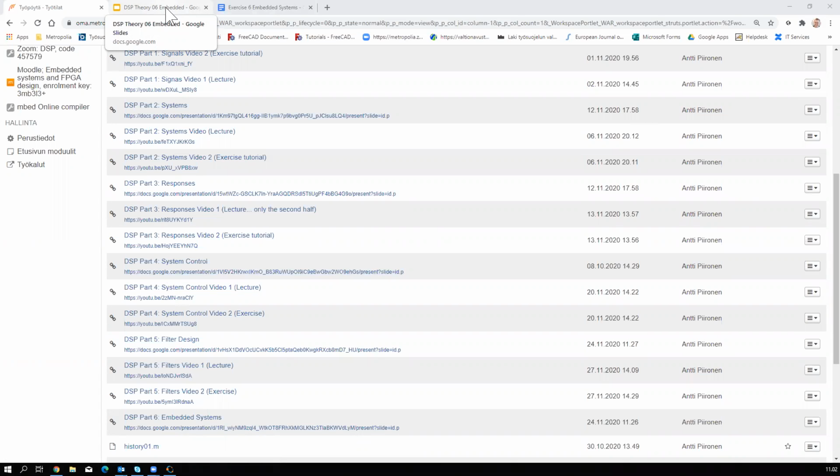Of course, when you are using a more advanced language like C, you can put floating point numbers even in 8-bit processors, but all the floating point calculations will take a lot of time on an 8-bit processor.